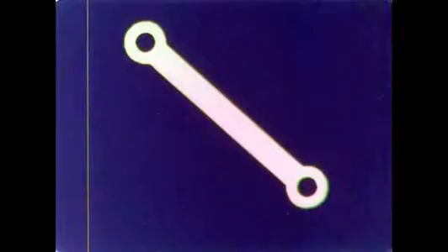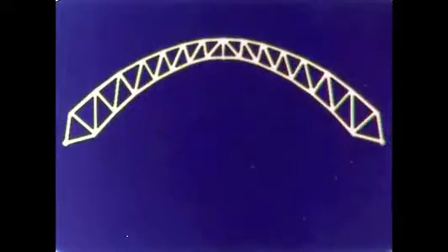The overall pattern of elements is referred to as the finite element mesh, and this pattern will be unique to each new problem. The initial step is to design this mesh, and for this we must first decide what kind of elements we'll use. One-dimensional rods, or two-dimensional triangles, or quadrilaterals. Or three-dimensional blocks, or a combination of different kinds of elements.